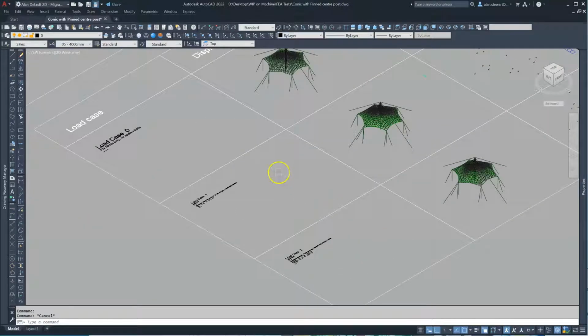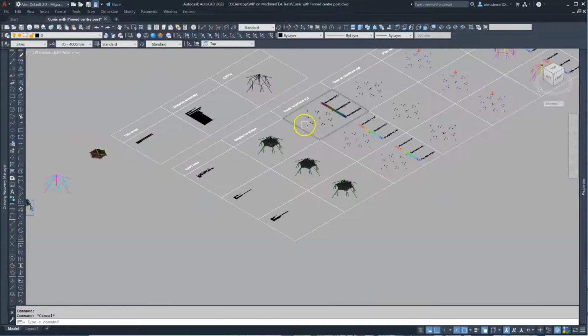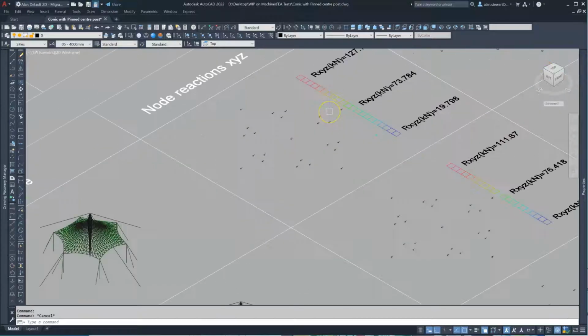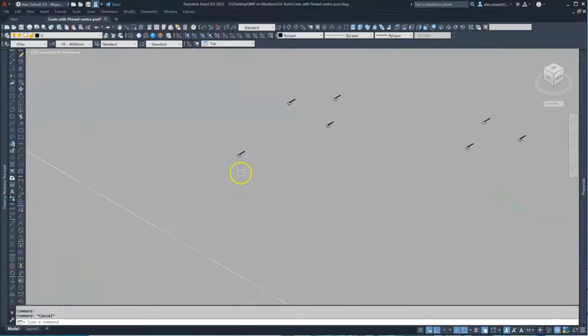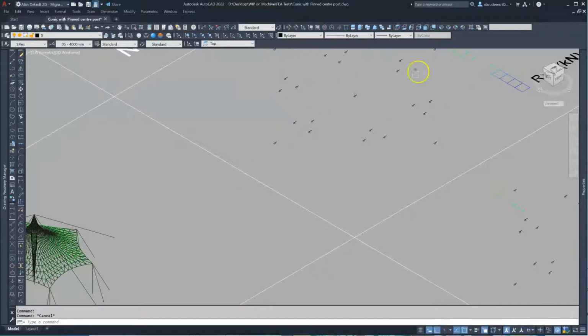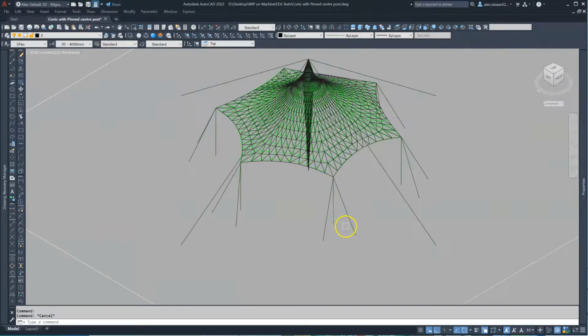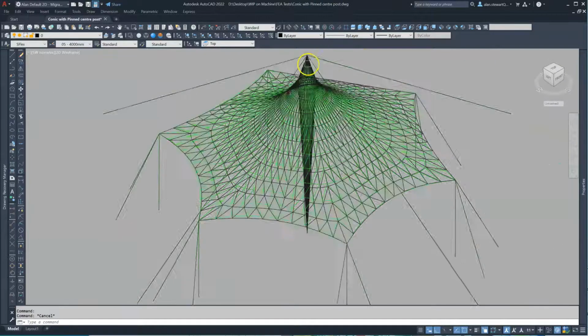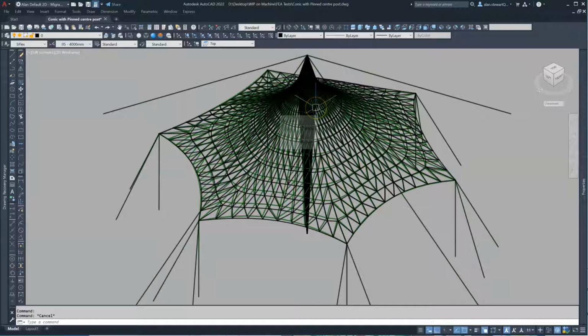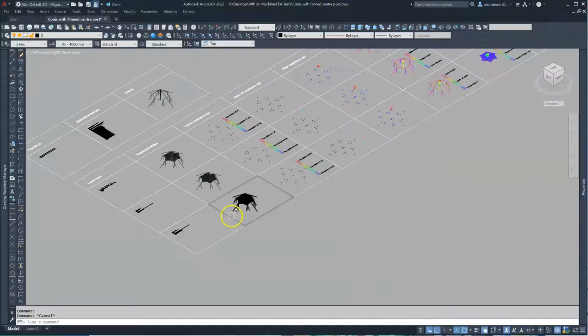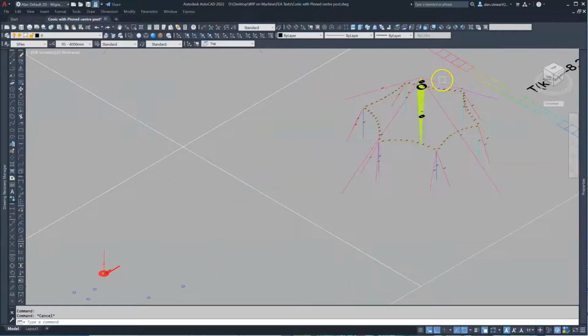We applied the same loads to the structure for load cases 0, 1 and 2, and when we review the plotted results, we can now determine the tensions in these 4 ground cables that anchor the top of the post, and we can see now the top of the post is restrained, so it does not move like it did in the previous example, but we can see the asymmetry in the cable tensions.